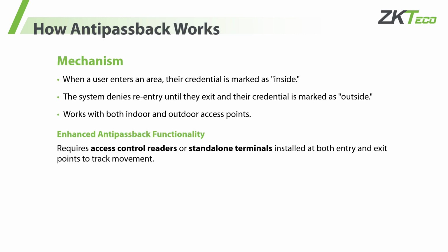So how does anti-passback work? First, when a user enters an area, their credentials are marked as already in the area. Second, the system denies them re-entry until they leave the area, and their credentials are marked as already outside the area. Third, it can be used with indoor and outdoor access points.